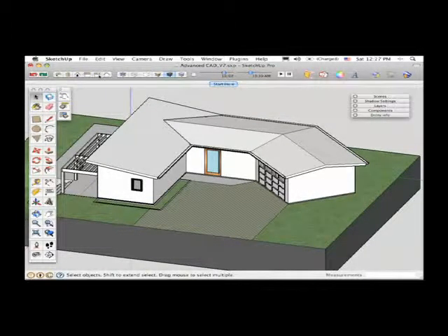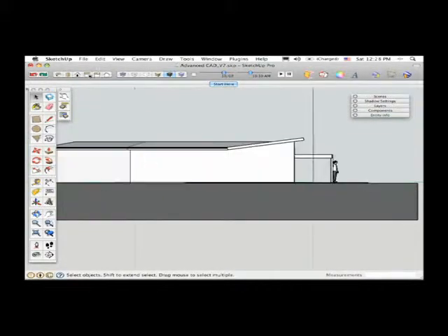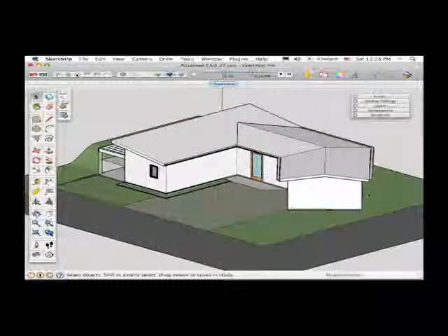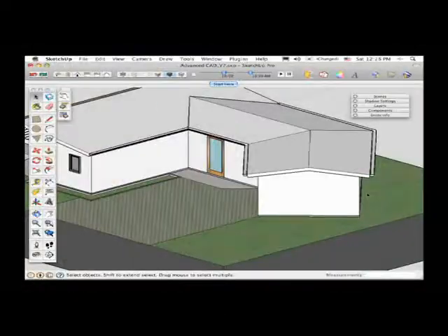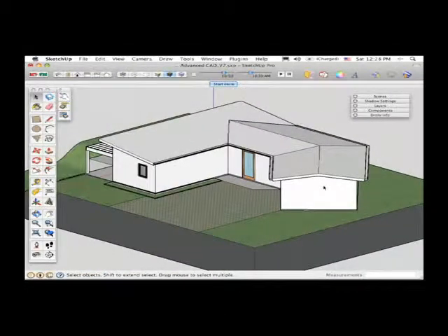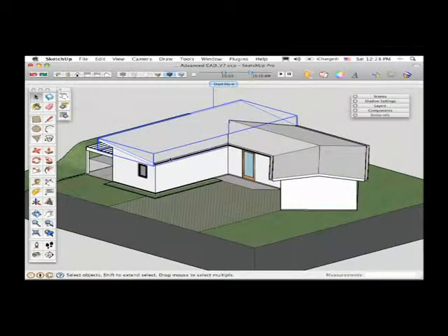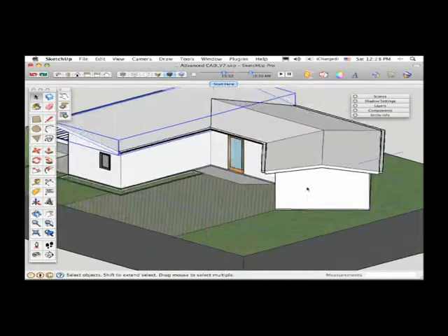Typically, when you're working in SketchUp, you have the option to easily cycle through some of the default elevation preset buttons, but when it comes to getting the elevation of walls that are at an angle relative to the axes, one of the things that you have an option to do is go into that particular object. In this case, you'll notice that if you click around in the model, different objects in this file are grouped and made into separate components, including the walls.